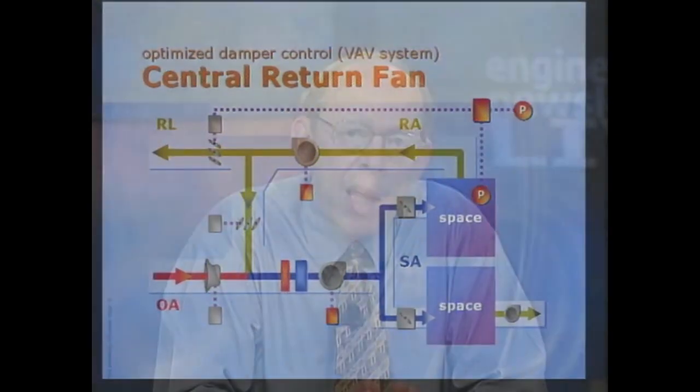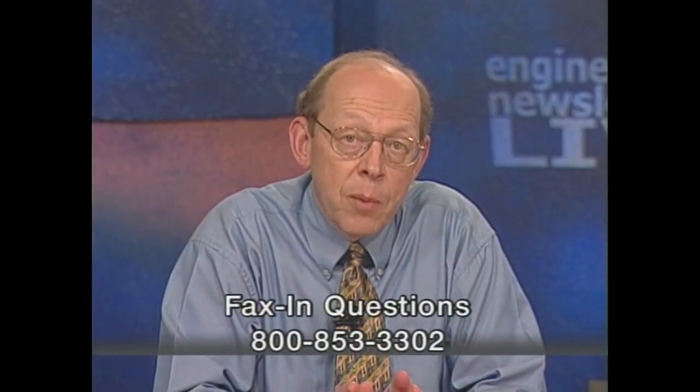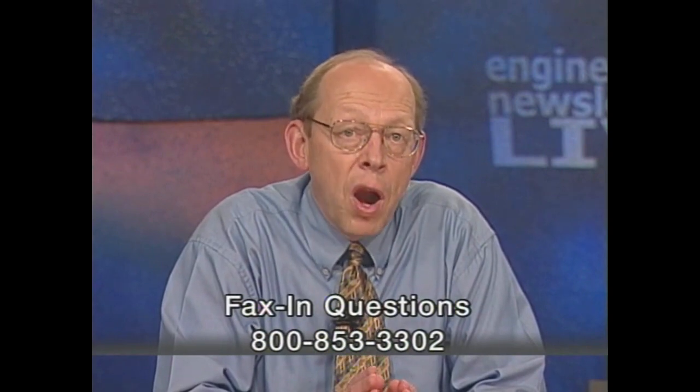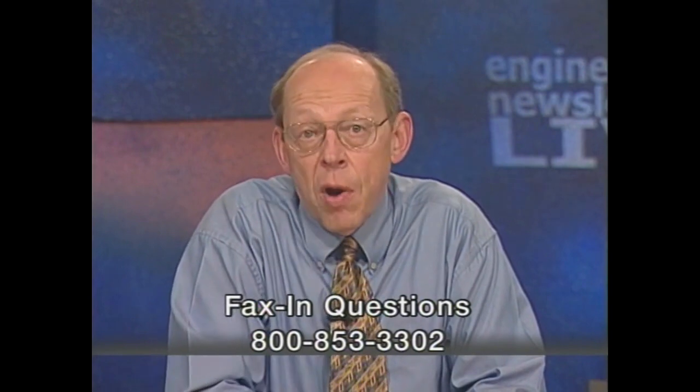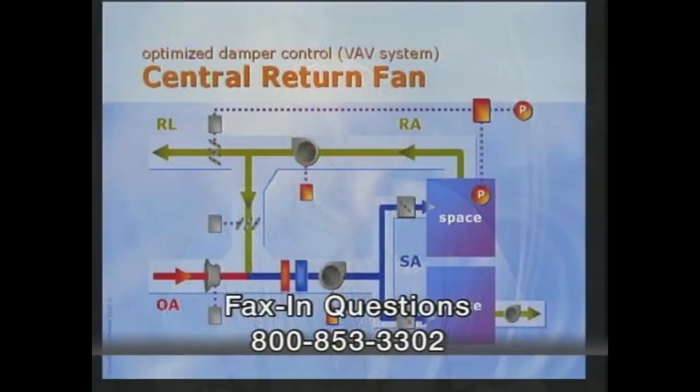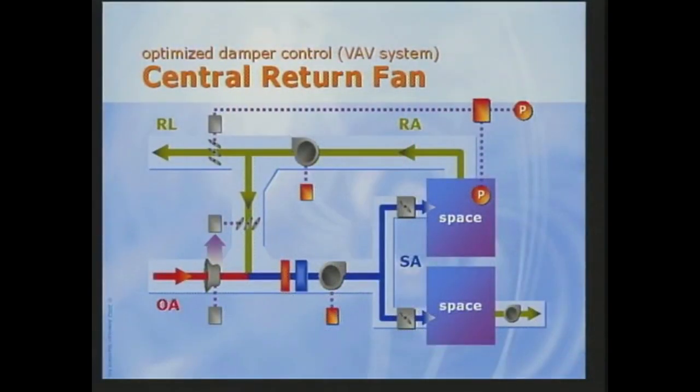Note that none of the dampers are linked. Each has a separate actuator. This is a key requirement for optimized damper control, which we discussed in more detail in our March 2000 broadcast. Using this approach, we may not even need to sense static pressure in the turbulent return air plenum.